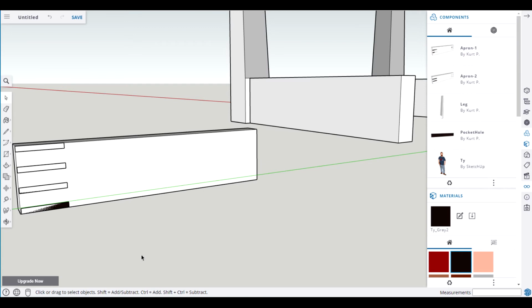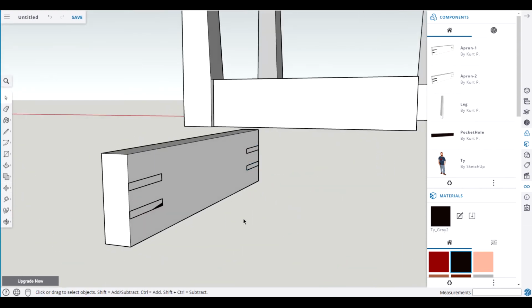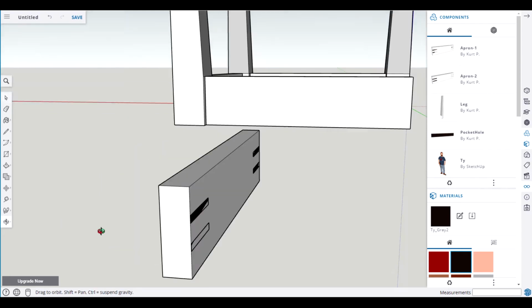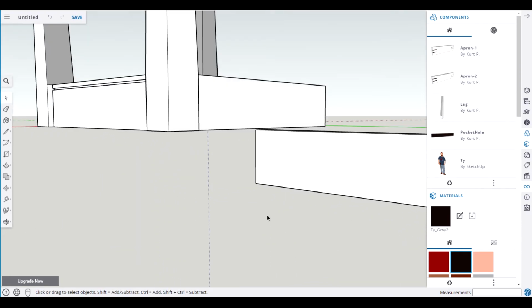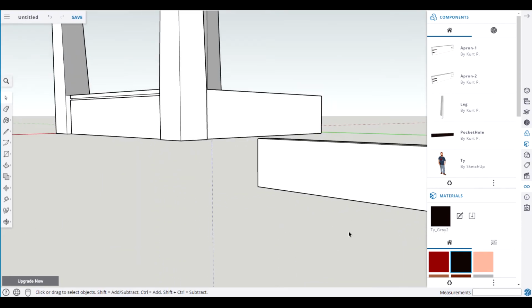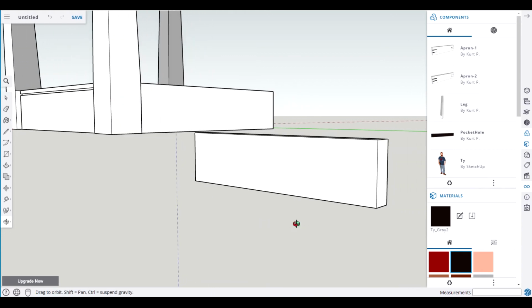displayed. We're going to highlight pocket hole, highlight pocket hole. Delete, delete. Then we're going to hold down the control key and click M. Grab one of these, drag across, control key, snap, boom, space bar. And let's turn to free space to get that stuff highlighted. And let's go ahead and H the pan, and now we have it here.